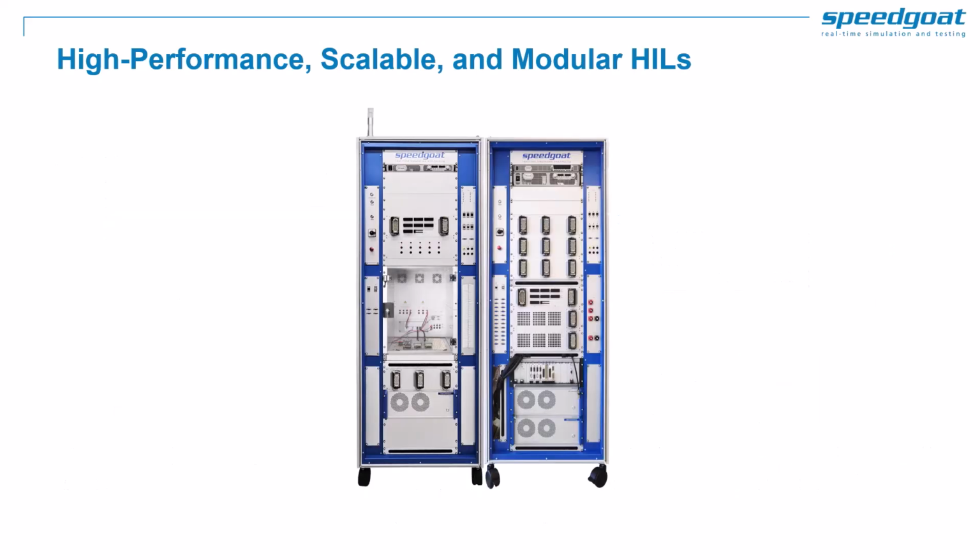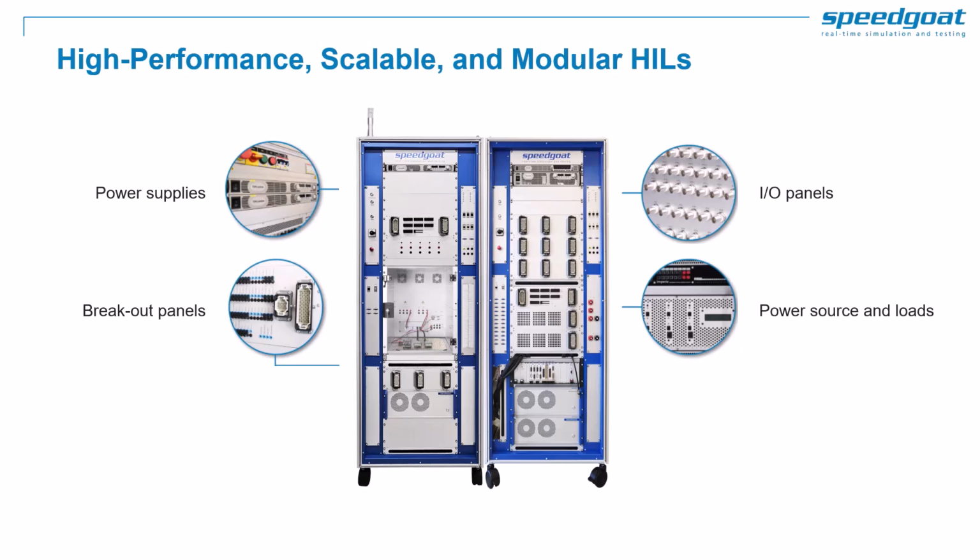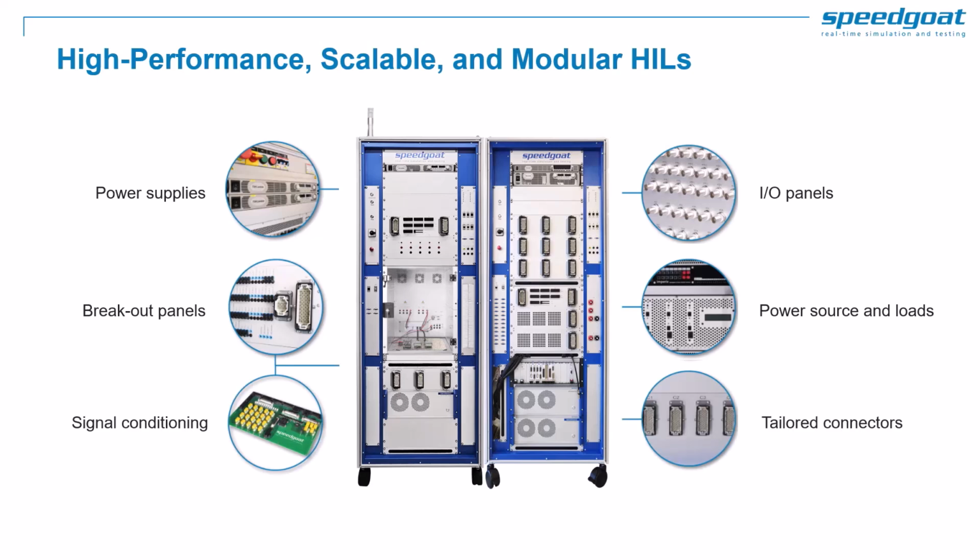Implementing a HIL system can be complex and time-consuming. But it doesn't have to. We provide you with all the specific expertise so that you can focus on your core task, the testing and validation of ECUs. With the help of our project management and production teams, we can provide you with fully customized rack systems, including rack-mounted HIL simulators and easy access to all signals via breakout and I/O panels. We will integrate power supplies, actuators, inverters, and any kind of power electronics, as well as project-specific PCBs for signal routing and conditioning.